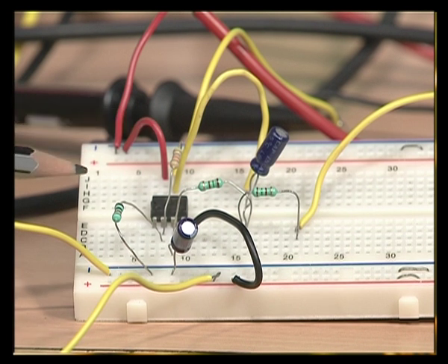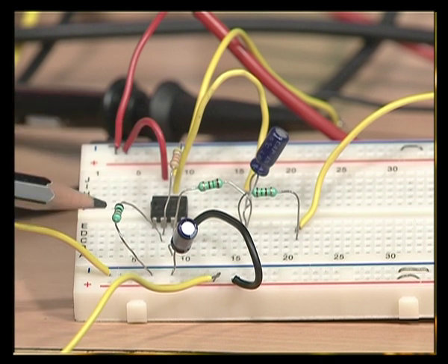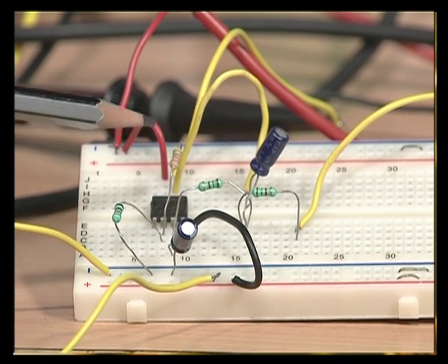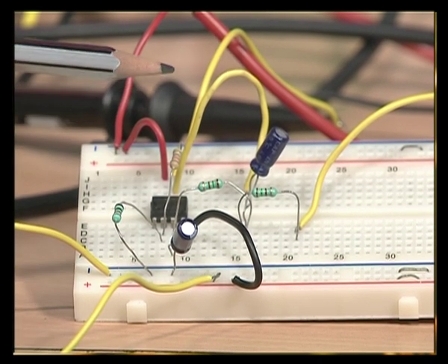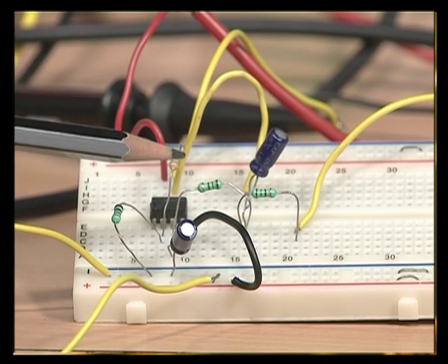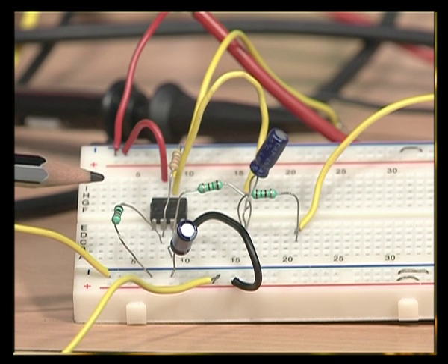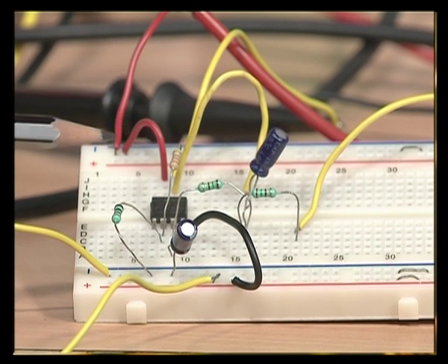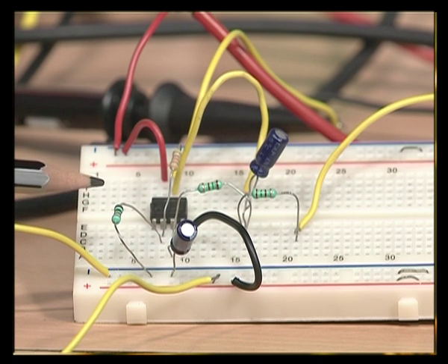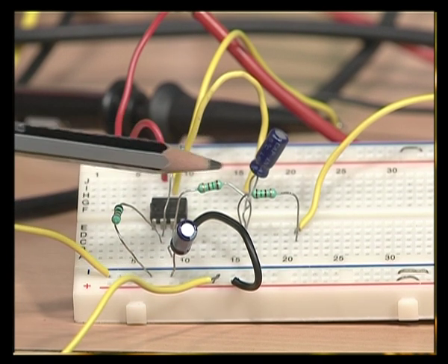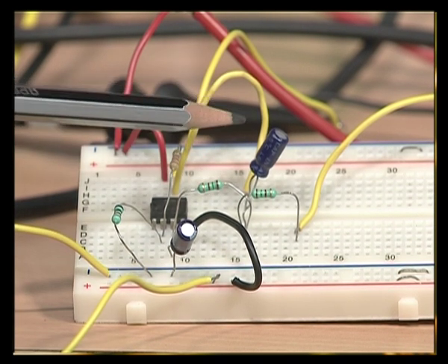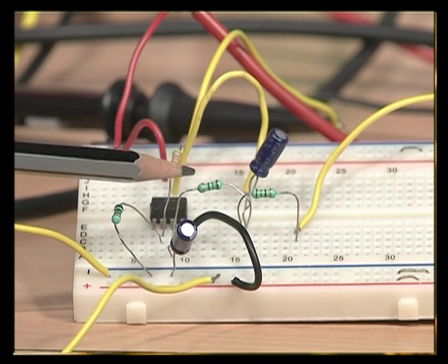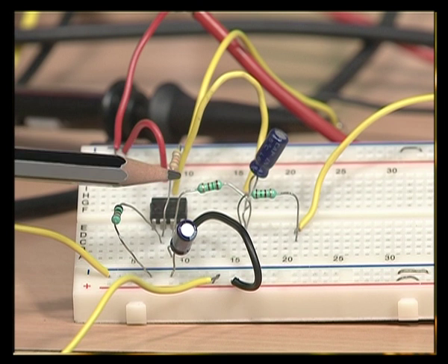Now, the resistors here are R1 and RF. This RF and this R1 will constitute the gain section for the operational amplifier. The resistor values here are 5.6 K for RF and 10 K for R1. These two resistors will set the gain of the Butterworth to be 1.586, and in the RC sections here, the R values are chosen to be 150 ohms and the capacitance is chosen to be 1 microfarad. With these values, the cutoff frequency is set to 1 kilohertz.